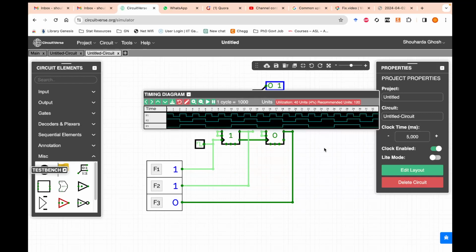In fact, this is the method using which, in a variety of electronic circuits, when we have a single frequency source, let's say a 1 gigahertz source, and I want to generate lower frequency clocks like 125 megahertz or 250 megahertz, I'll be using counters, and corresponding to their location and which bit, how much frequency I want, let's say 250 megahertz, I'll be using the second flip-flop output, because that's f by 2 square, f by 4, and based on the nth bit I will have a 2 to the power n factor of reduction for the frequency of oscillation.